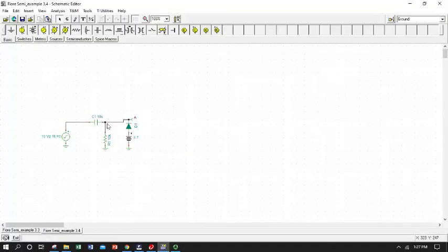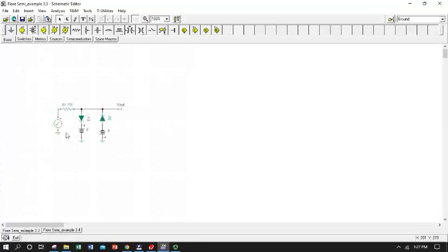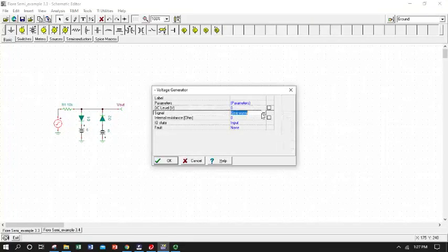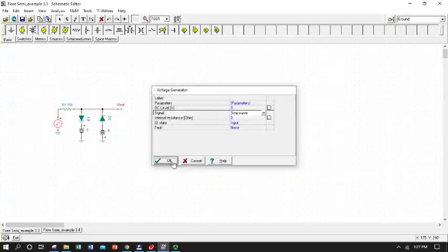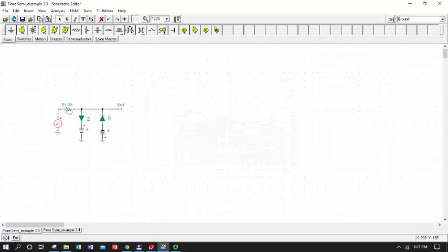So an easy way to take a look at that and get your arms around it is to use our TINA simulator. And so we've put a couple of clippers in this circuit. We have a sinusoidal waveform, which is 12 volts amplitude, so that's 12 volts peak, and it's got reasonably high frequency, which really doesn't matter from the standpoint of this circuit. We've got our current limiting resistor, which can really be any value in this case, but it's pretty high because we don't want to damage our diodes or have excessive AC current flowing through our sources.